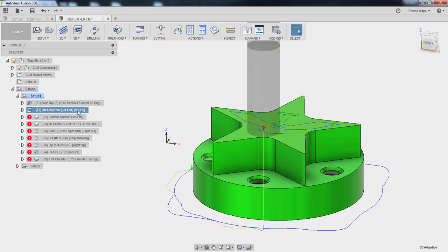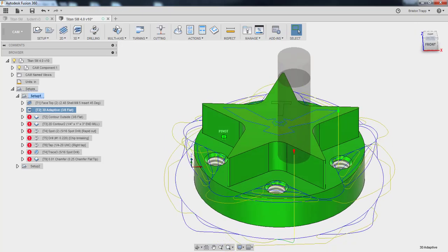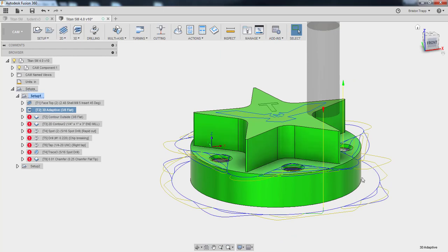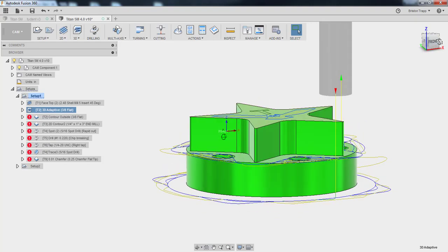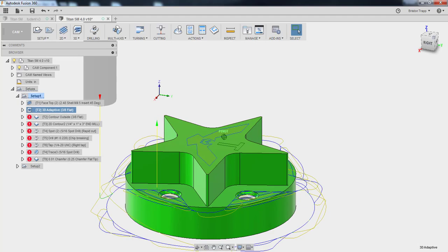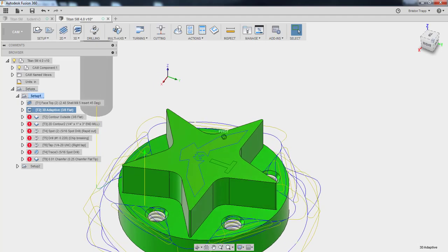Notice it takes a while to load. Go ahead and look at our toolpath. You should see 2 different layers. If you notice any really small whisper cuts, a non-efficient method of machining, you need to go back and make sure you increase the radial stock to leave.